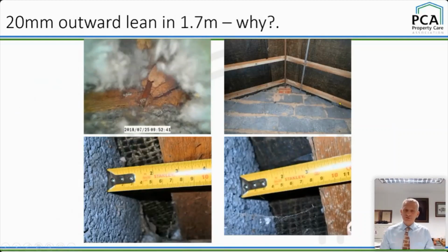It's a lack of lateral restraint. Okay. And rather than try to photograph a spirit level in the roof, just to demonstrate that that rafter is straight and true, all right, and so is that one. And when we've checked it, at the bottom, the gap between the blockwork is about 60 mil, and it's over 80 mil there, okay? And that's at the top, all right, that's at the top. So it's moved out. So why?